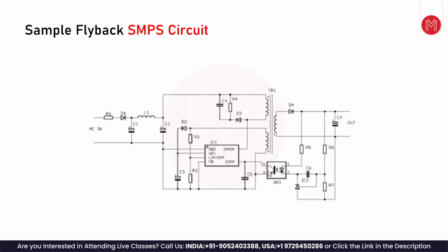And when the transistor is turned on, it's more biased, and the output goes down, right? Typically that's how the transistor works. With more bias, the output goes low. It works like an inverter. So this voltage drops, the compensating voltage drops, and the duty cycle reduces. Then this current will be forced to go down, and this voltage will be forced to go down. Whatever was trying to increase beyond 9 volts will come back down to 9 volts.